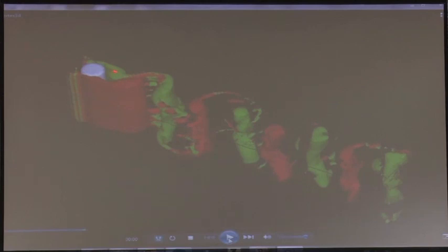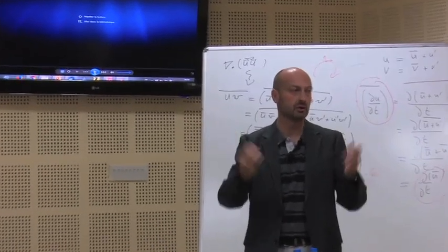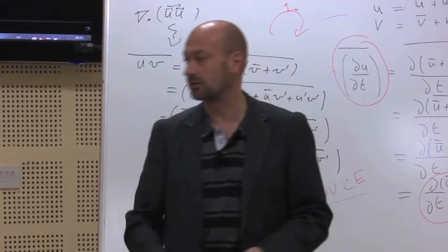So you see in green the vortices which are rotating counterclockwise, and in red clockwise. Okay, and then it's a 3D simulation which is time dependent. It's completely unsteady. So you see the big vortices, but you see also the small vortices which are generated on the side of the vortex. So this is a typical simulation with direct numerical simulation. You solve only the Navier-Stokes equations, you increase the Reynolds number, and then you see the vortex shedding, and you see the turbulence which is appearing.